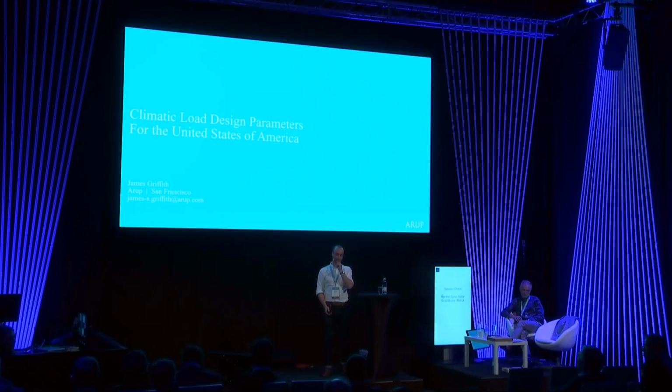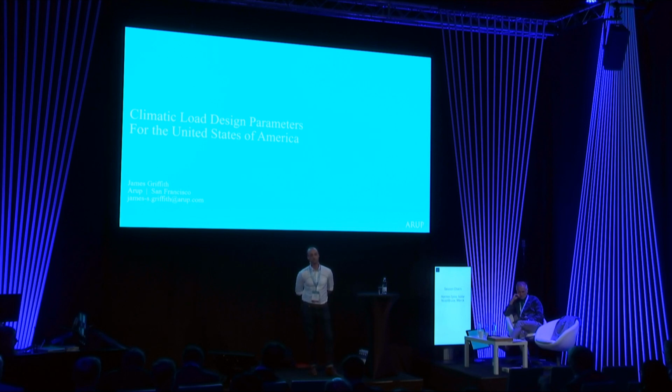Okay. The second one is, how do you plan on applying this information once you've got results? Because I imagine there's two sides of it. One would be strength, where you're looking at sizing your silicone joints for the climate load that you end up with. And the other would be more of a service condition where, if you've got positive and negative isochoric loads and they're quite high, you have a kissing condition or a pillowing condition like you talked about. How would you design for that? A pressure equalization, or how do you find a value that you design for?